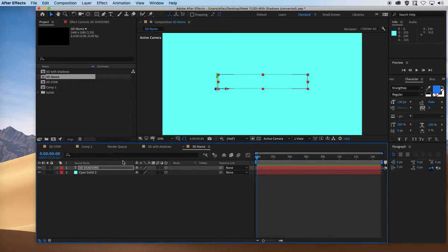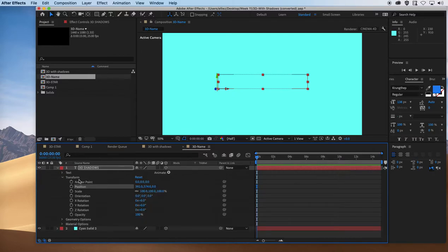As soon as you do that, your text disappears because both of these layers are in the same plane. So we need to change the Z index, which is the position of my text in relation to the internal camera, to a minus number so that I can see my text. I can simply choose -1 in the Z panel here, and then my text pops forward.